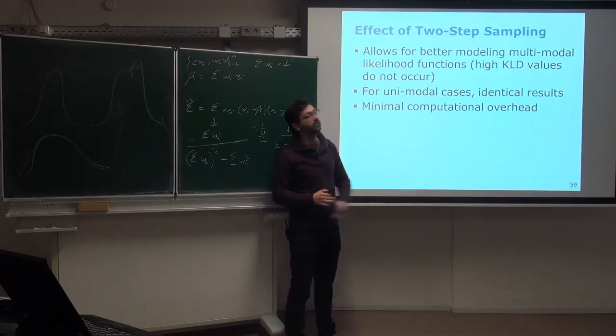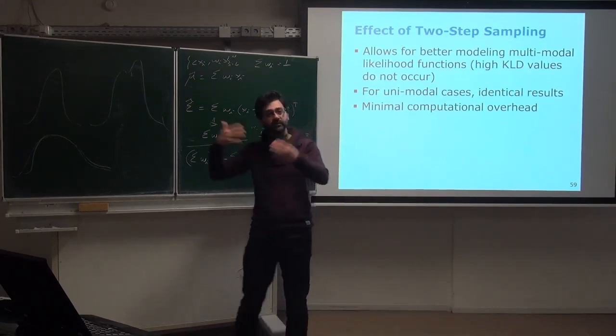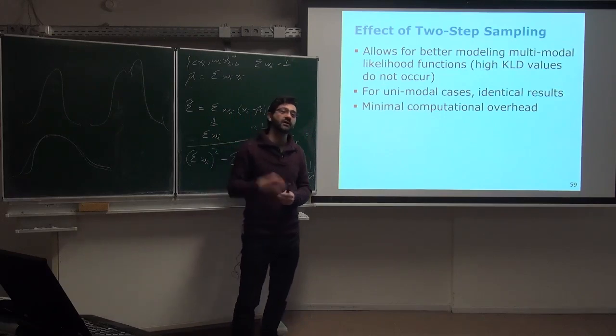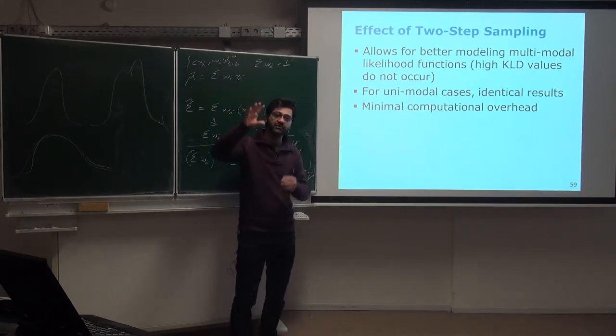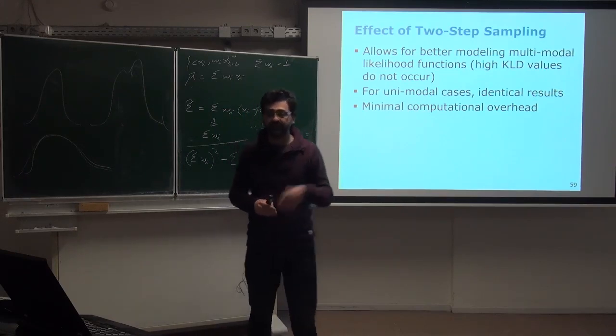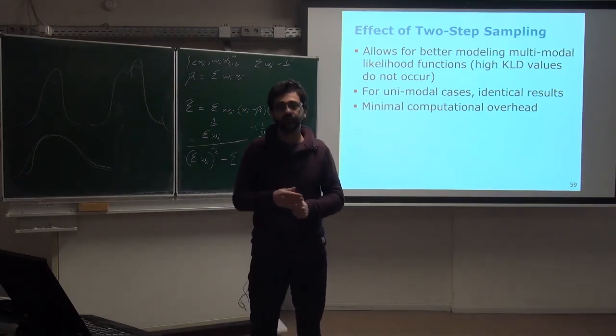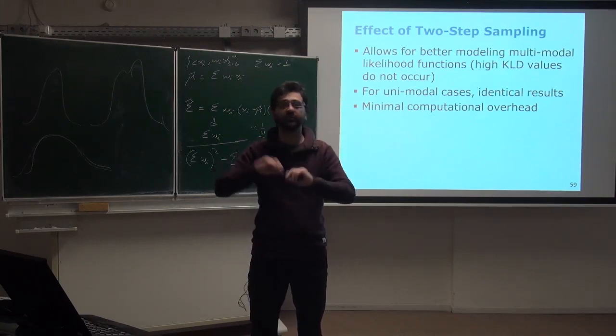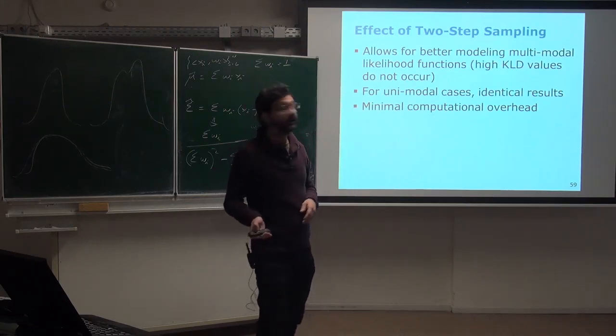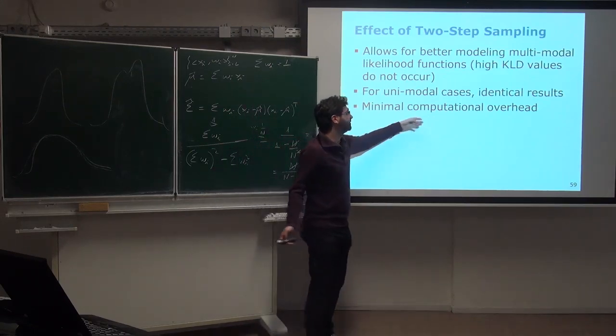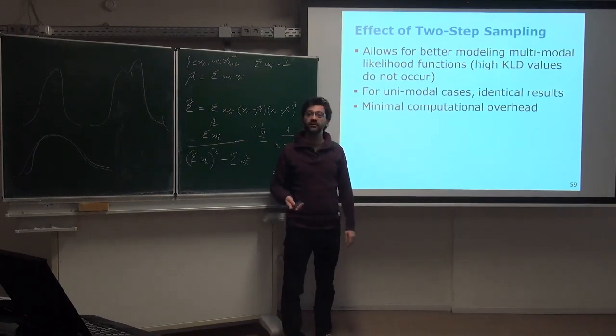There is a minimal overhead because you need to do multiple scan matchings instead of a single scan matching, and then an approximation of the likelihood of the distribution, so computing this mean and this covariance. But sometimes this small overhead is actually worth the price to pay.